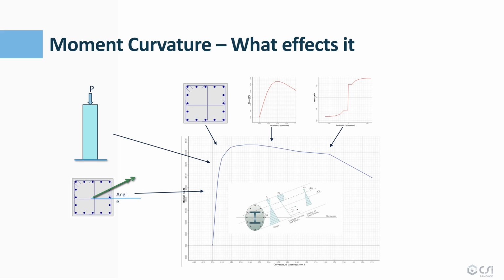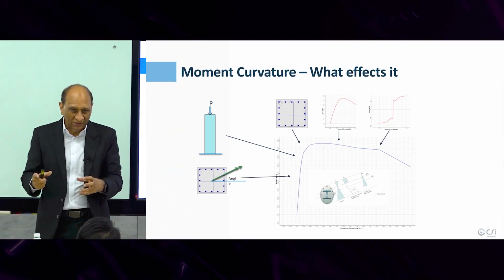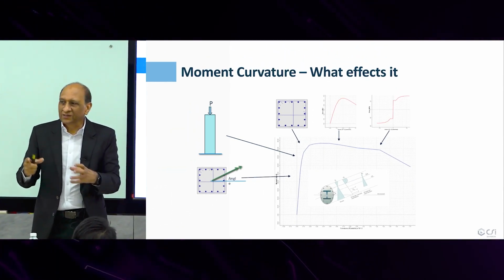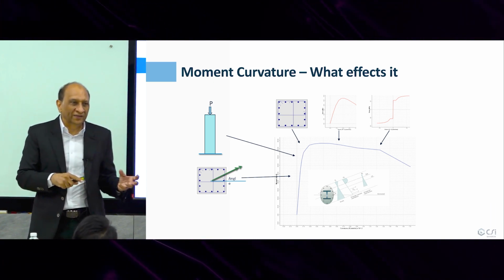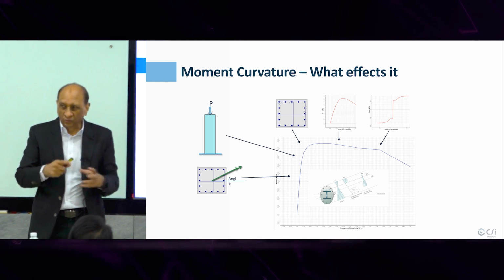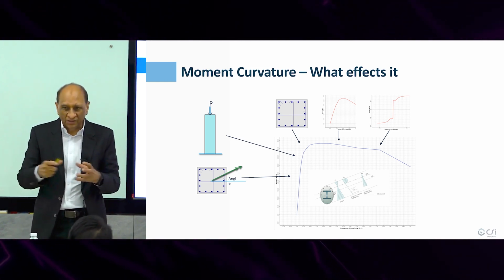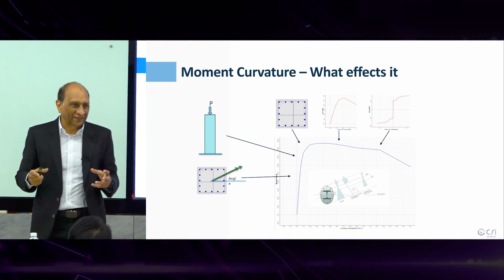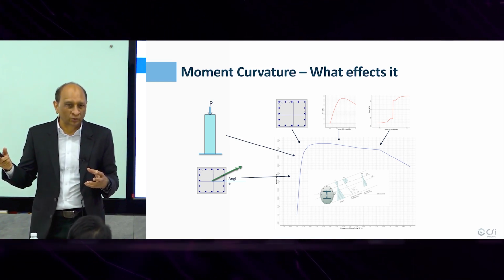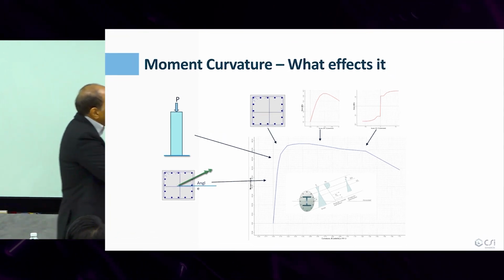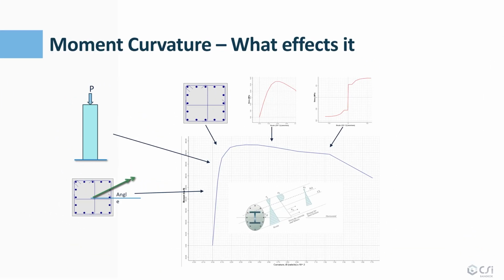That means we now have a very good tool to include all these variations, very specific variations in a structure for which the strength design will give you the same answer. To include them in the investigation, so we can make the distinction between good and bad and sift them this way, right? Not just looking at the DC ratio of the moment to decide what to do with it. So that's the advantage, and we use the general equation for all this generation in CSI Col.